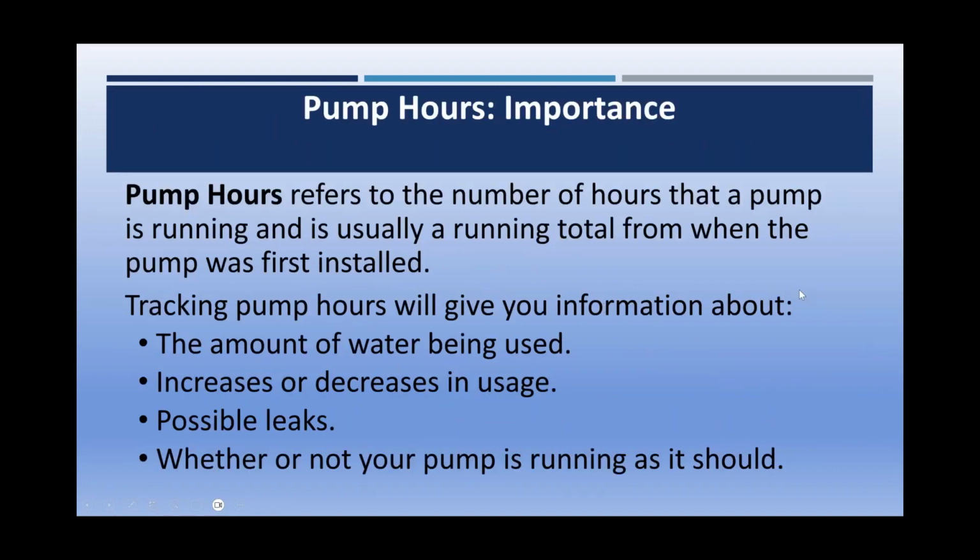So pump hour refers to the number of hours that a pump is running, and is usually a running total from when the pump was first installed. So tracking pump hours will give you information about the amount of water being used, increases or decreases in usage, and possible leaks. And again, whether your pump is running as it should run.